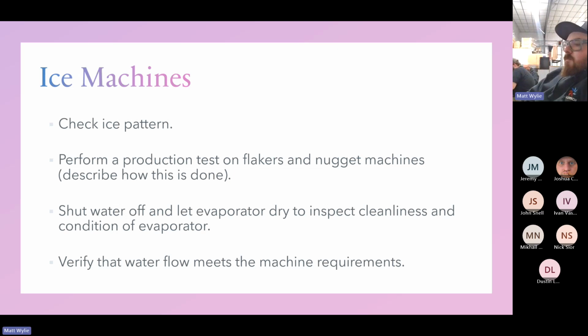So KT is the kit. Yeah. So the 43 is the element size number. The next letter is the refrigerant code. What's the refrigerant code on the TXV, Matt?